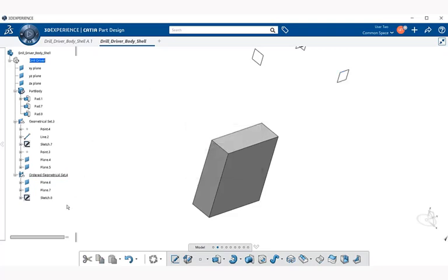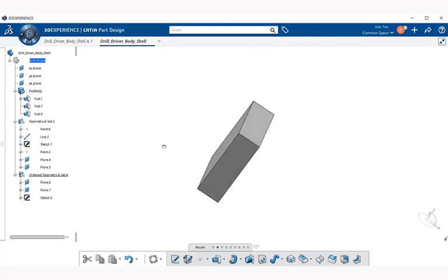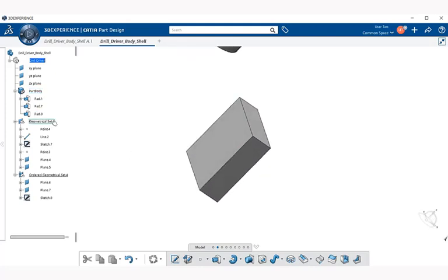That's the example I wanted to show you: the fluidity of the geometrical set, where I can place things in here and move them around. Whereas in an ordered geometrical set, it timestamps you and locks you into a certain place of when that was created and what was created, the same as a part body. So those are the basic differences between geometrical and ordered geometrical sets.